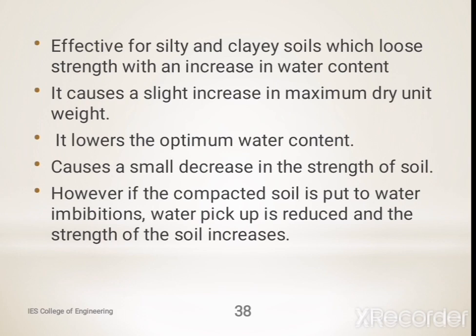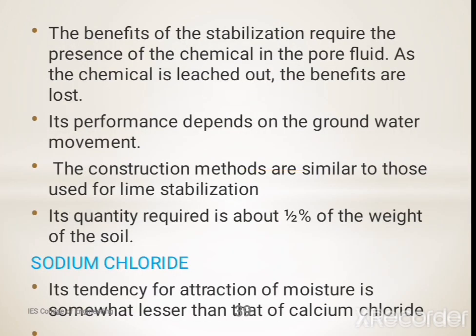It causes a slight increase in maximum dry weight. It lowers the optimum water content. Causes a small decrease in strength of soil. However, if the compacted soil is put to water imbibition, water pickup is reduced and the strength of soil increases. The benefits of the stabilization require the presence of chemical in the pore fluid. As the chemical is leached out, the benefits are lost.